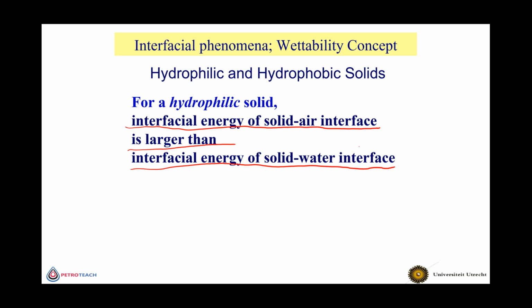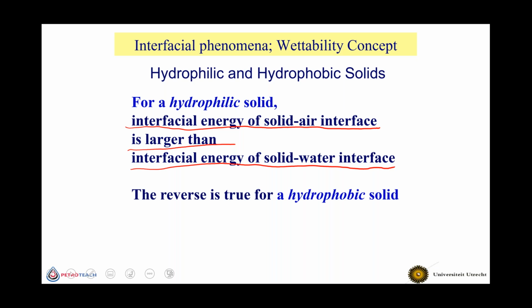And that is behind the concept of wettability. The whole system goes to a lower energy state. And you saw that here. Of course, the reverse is a hydrophobic solid, which doesn't like water. In that case, the solid-air interfacial energy is less than the solid-water interfacial energy.